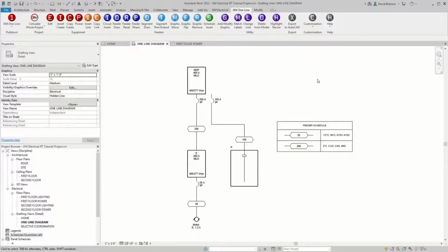For branch circuits, you generally want to have home runs. And if you put tick marks on the home runs, it's going to do tick marks based on whether Revit thinks it has a neutral or not. So you need to get the neutral correct for your branch circuits, which is fairly straightforward to do, and I'll show you that in a moment. For feeders, you need to do that differently because the way that the neutrals work for branch circuits, it does it the same way for panels, which actually corresponds to transformers as well. And there are times when it puts a transformer in that you don't. And so you need a different way to say, yes, Revit, I know you think there should be a neutral here, but I really don't want one, so please leave the neutral out.